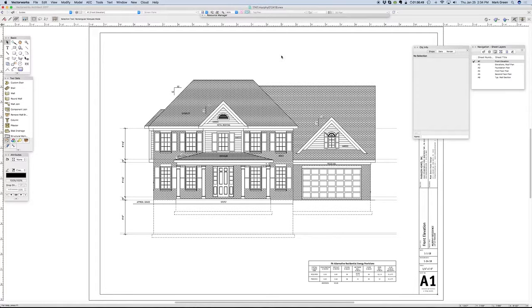Step one is checking the model. You're checking that all 3D items, any item actually, that is on a design layer is in its proper class. So to do that, I would go to the Save Views, pick a floor. We'll just start from the bottom and go all the way up. So you'd be working on the basement, the first floor, second floor, and all the way up through the roof.